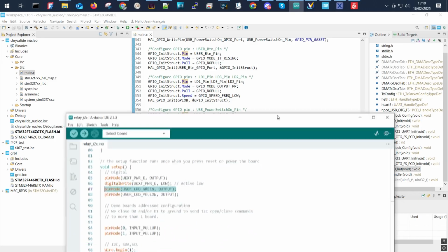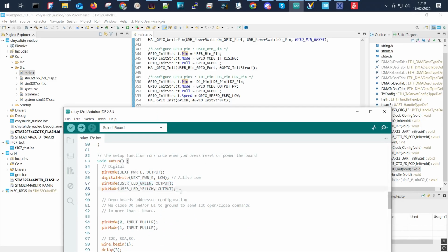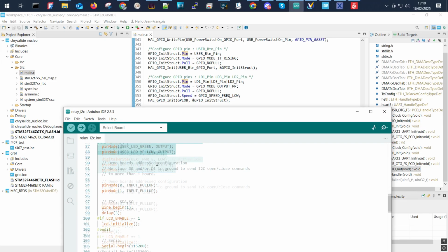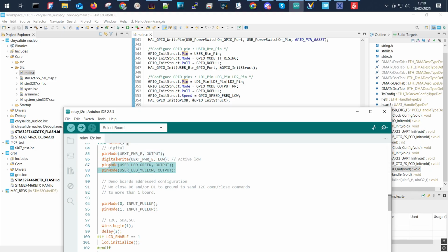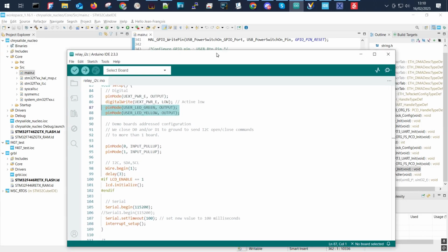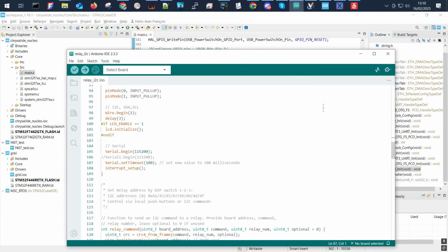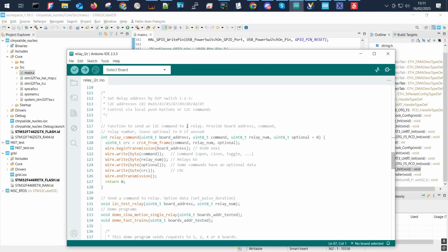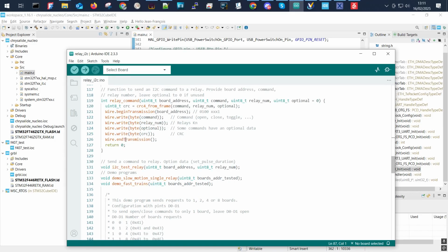And now we see that with the Arduino IDE, how are we going to use the microcontroller with its own capabilities like this. And we see that at this point everything has been abstracted away. We cannot really go into this particular configuration unless we do the same kind of work, that is read and understand the hardware manual, and start to handle the registers of the microcontroller.